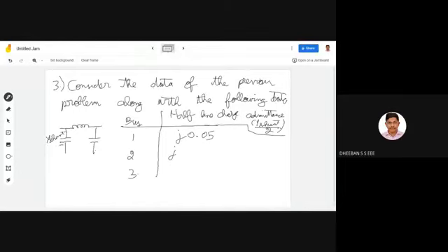So that you have to consider mainly at your self admittance parameter, that is with respect to your diagonal parameter. If considering the diagonal parameter, I have already told how the formula changes. It is very simple. Only this y shunt by 2 parameter will get summed up with your diagonal elements.